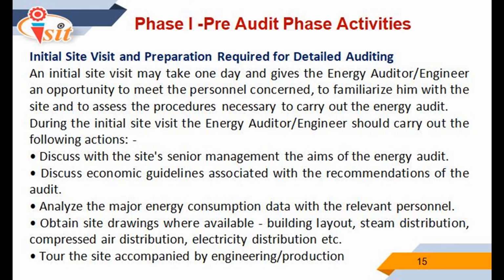During the initial site visit, the energy auditor should carry out the following actions. The first point is to discuss with the site senior management the aims of the energy audit. Second, discuss economic guidelines associated with the recommendations of the audit. The next important point is to analyze the major energy consumption data with the relevant person. Obtain the site drawings where available related with the building layouts, steam distribution, compressed air, electricity distribution, water distribution, etc. Touring the site by the engineer is the most important point related with the energy.